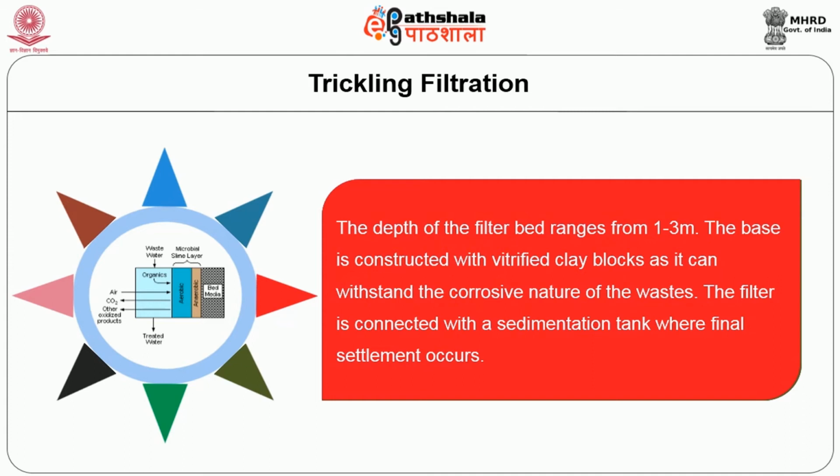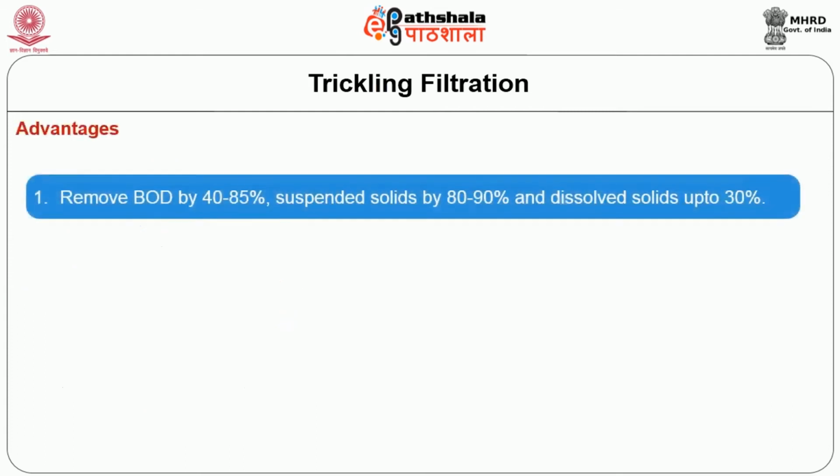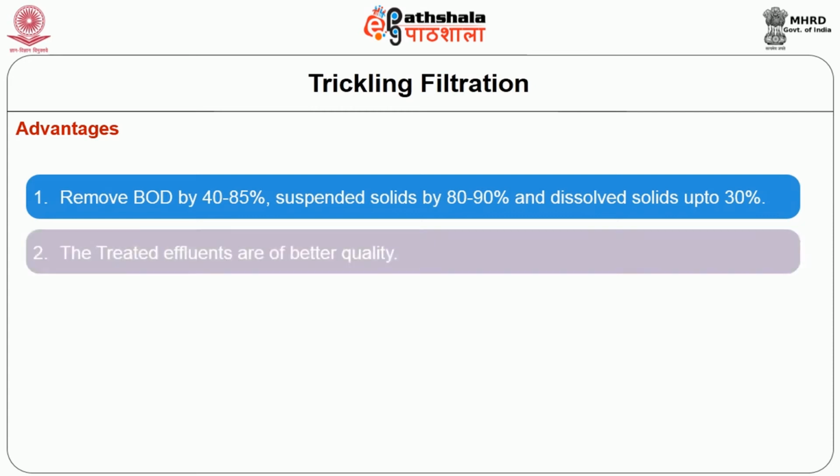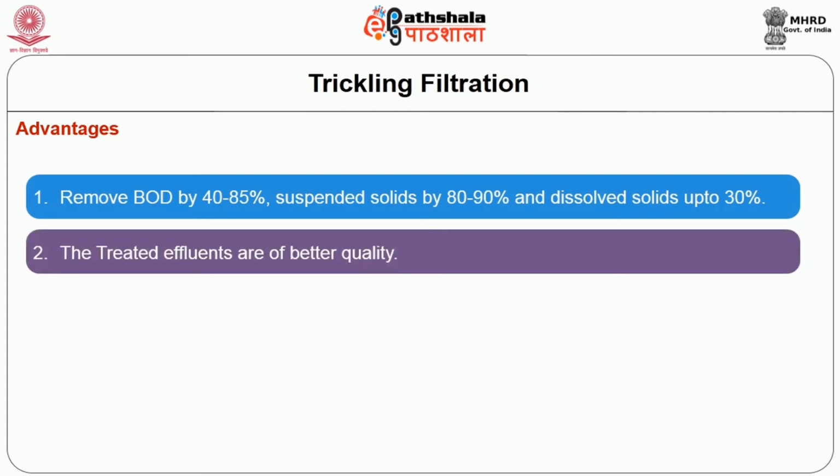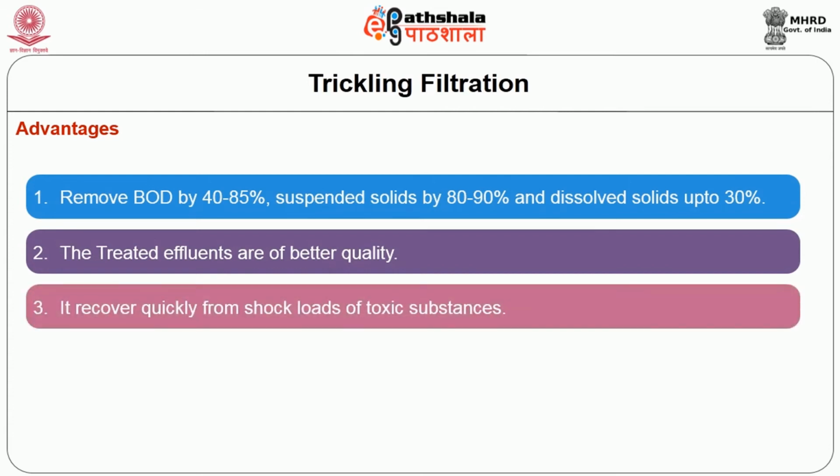The filter is connected with a sedimentation tank where final settlement occurs. The advantages of this technique is they remove BOD by 40 to 85%, suspended solids by 80 to 90% and dissolved solids up to 30%. The treated effluents are of better quality and it recovers quickly from shock loads of toxic substances.